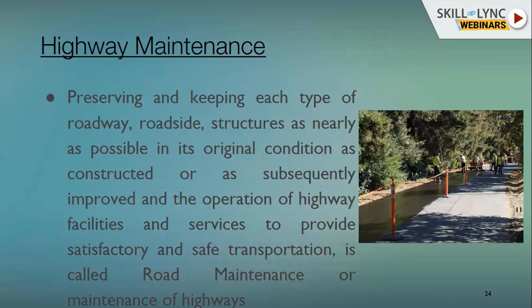Regular maintenance of the road. In some cases, the earthwork may just slip off from the road sections because of heavy rain or substandard construction. For that, quick reconstruction will be very important. In some cases, it creates a pothole in a section. Once the pothole is created, if rainwater is collected there, the water will start percolating through the road layers, and it will create damage to the road. So quick maintenance will be helpful for the long run of any highway project.